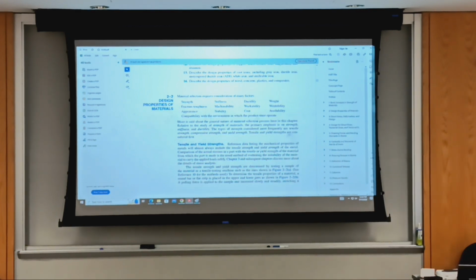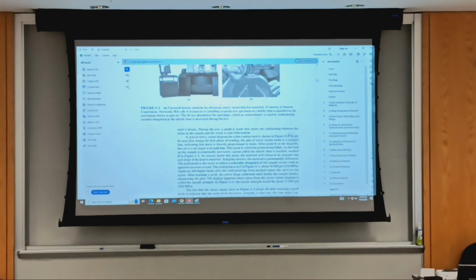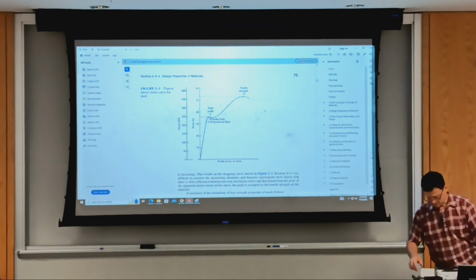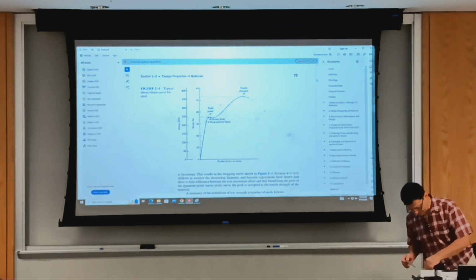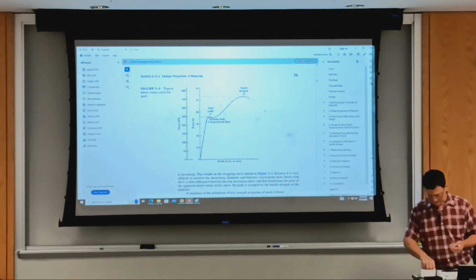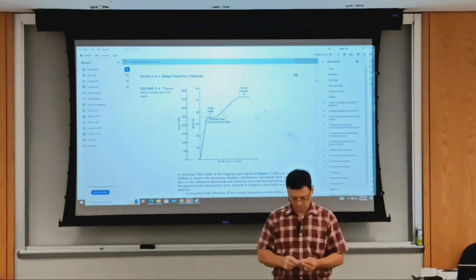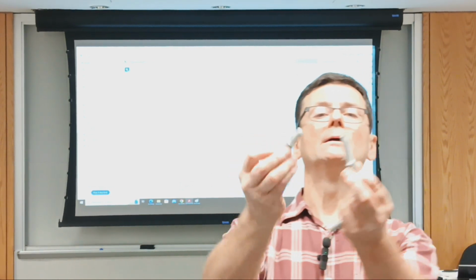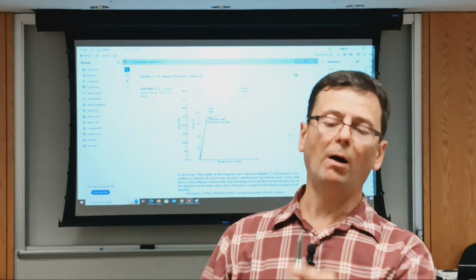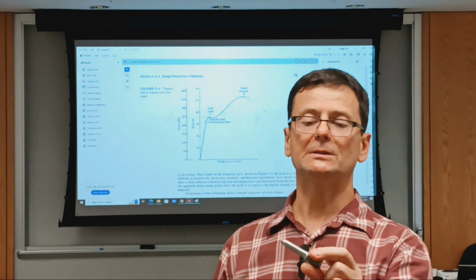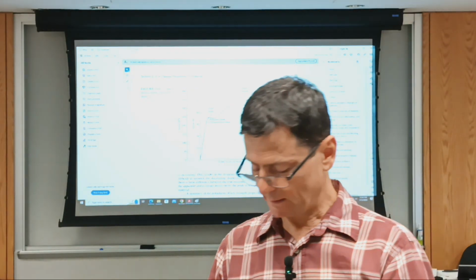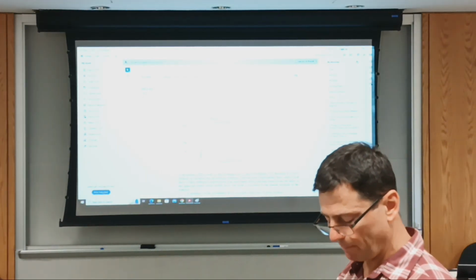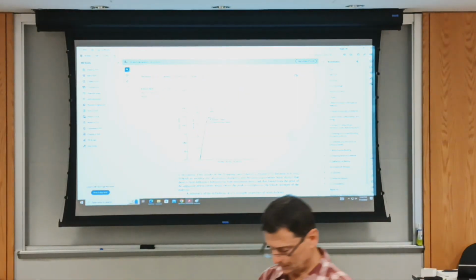Anyways, we'll be looking at tensile stress and ductility, and this shows the stress strain curve for a ductile material like this stainless steel is. I'm showing it first to the camera. So this is an aluminum specimen, and this is only part of it; I don't have the other piece of a stainless steel, okay? And just look at the way they broke. It's called cone in a cup, with a necking, a reduction in diameter.